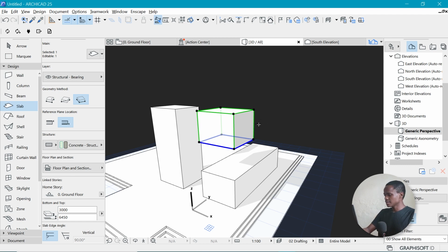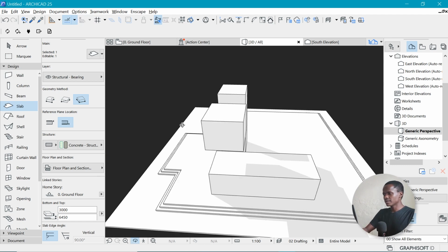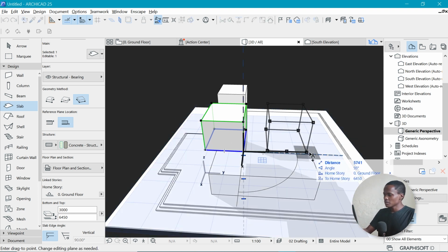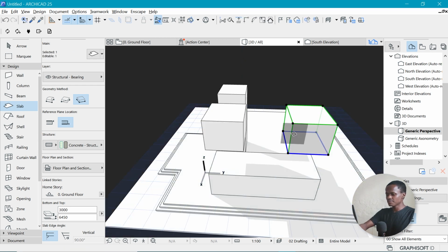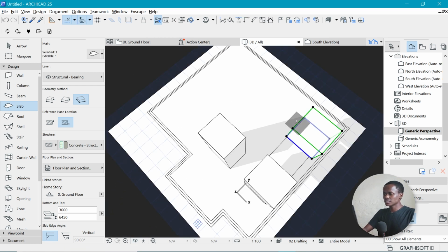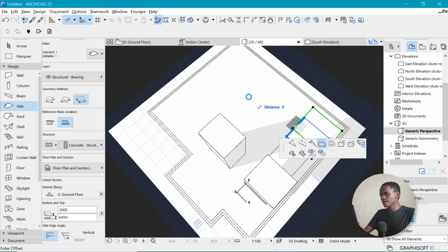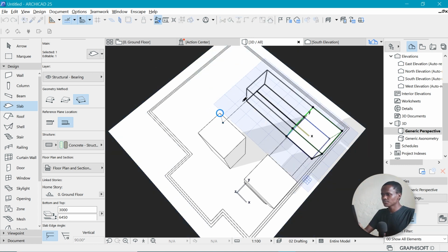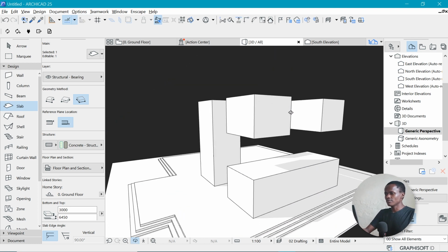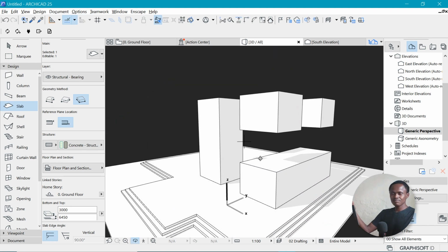Next is, I'd like to make the same copy, but this time on this other side. So Ctrl+Shift+D, make sure you hold down Shift in order to move this to somewhere here. And now we can extrude this by just clicking on the edge, and with the extrude option selected, you can see that now we have ourselves a form, and that's the basic form.